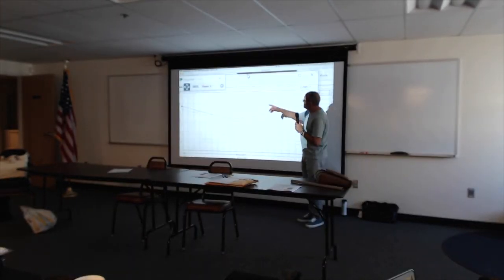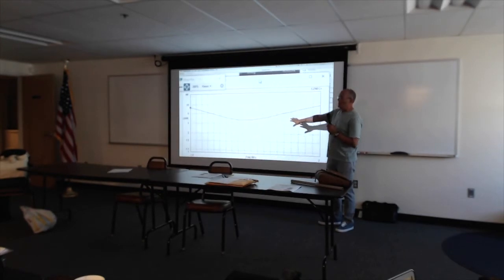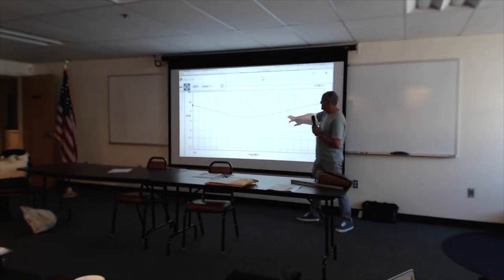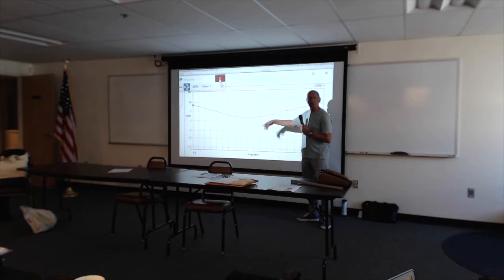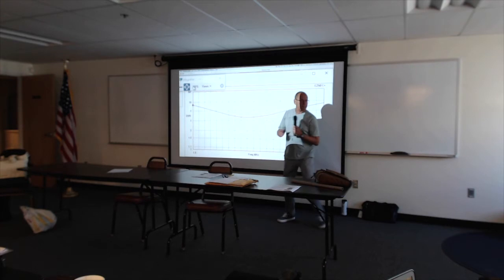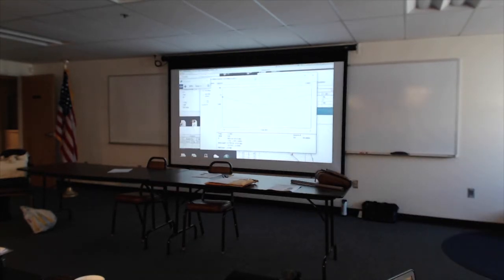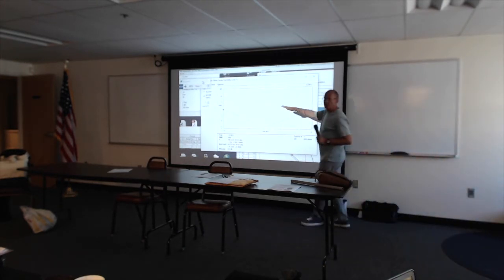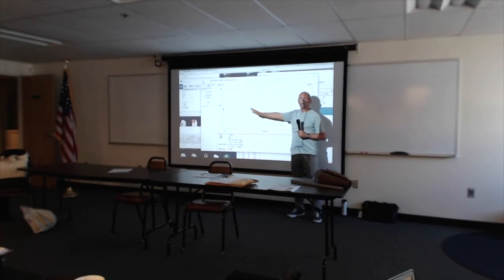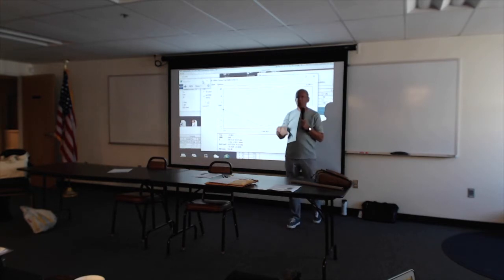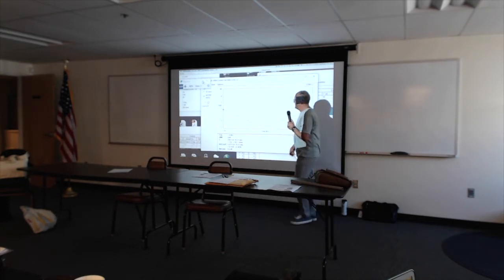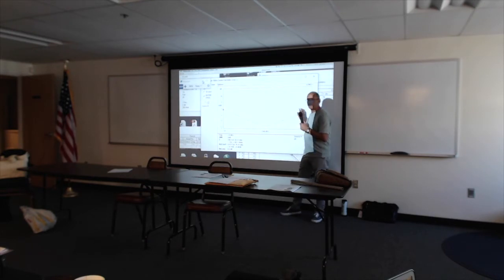Okay, so this looks really bad. This is because the impedance automatically defaults to 50 ohms. Phil, on the left side of that, put 100 ohms in there. Click Alt 200, and it brings the SWR down. This is right at the connection point of the antenna, because I didn't model a balun, didn't model any matching coils or anything like that. So it starts bringing it down within a reasonable range.